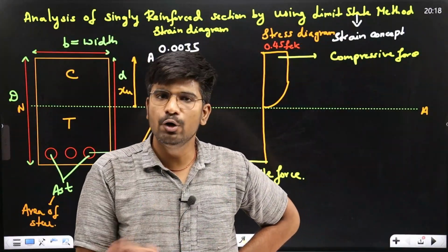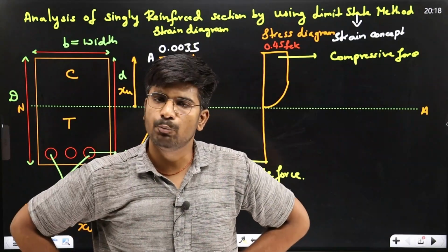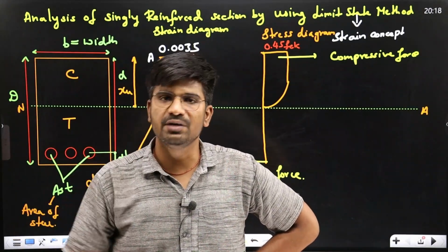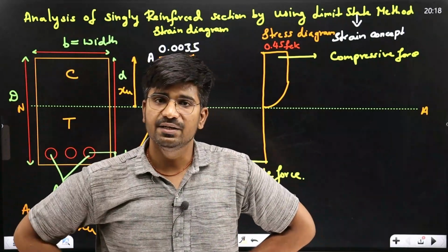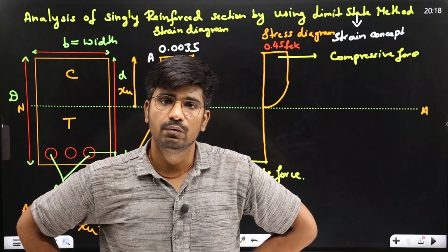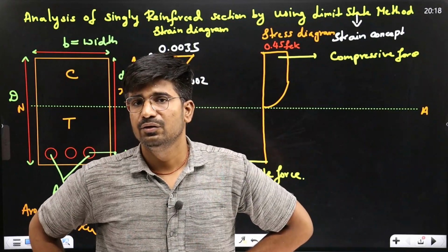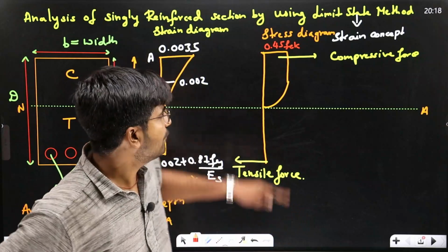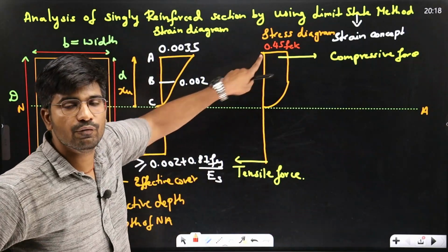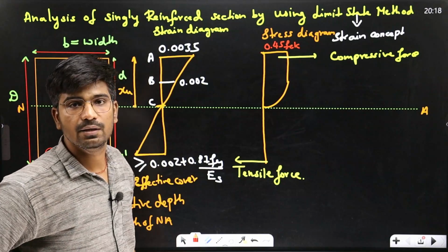Then for beam and all in your lab test, you divided with 1.5 factor of safety, and got 0.67 FCK. Again when you go for site, because quality control of concrete is very poor, it is very fluctuating, so again you have to divide it with 1.5. And now what is the value of stress you got? 0.45 FCK.